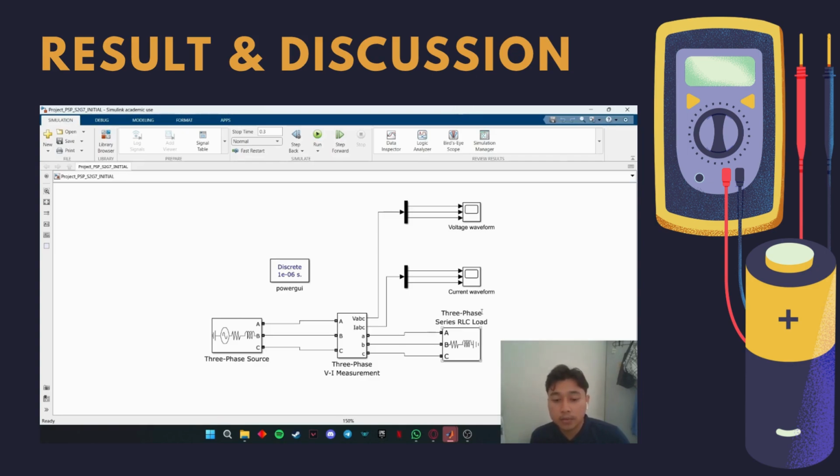For our group project, we need to simulate the distribution system and balanced three-phase fault type on Simulink MATLAB. As we can see here, this is the distribution system simulation that consists of a three-phase source, three-phase VI measurement, three-phase series RLC load, which is the consumer, and we also put a scope to see the waveform of the voltage and the current. I also set the stop time to 0.3 seconds, and then we need to run the simulation to see the waveform of the voltage and the current.